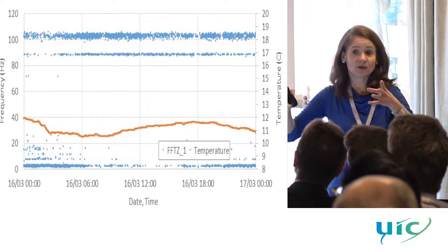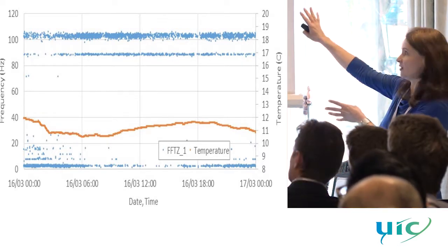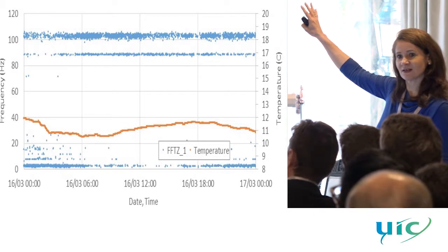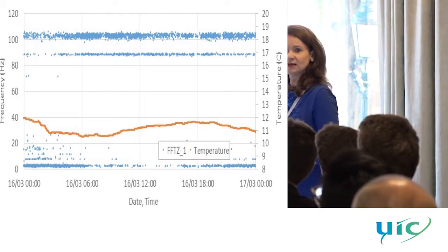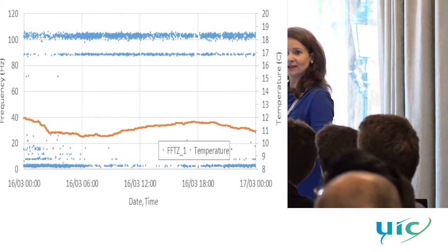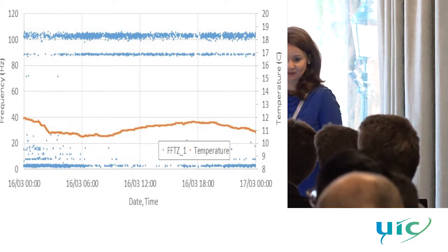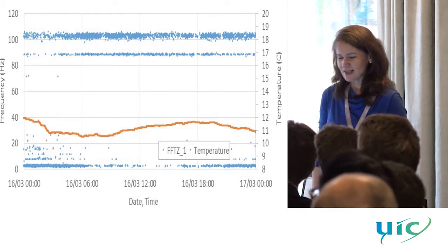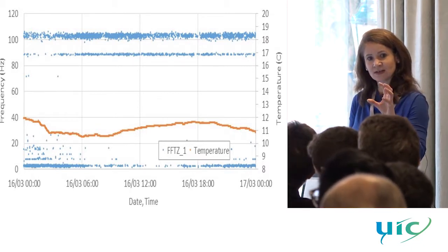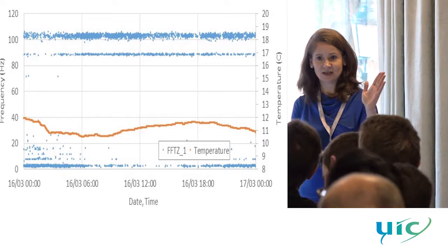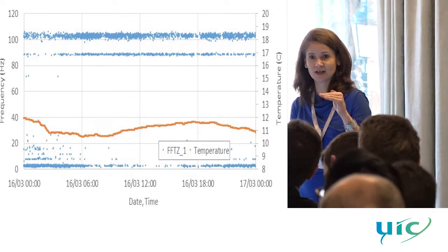Therefore, during the day, you've got more traffic loading, so the high-level frequencies relate to traffic noise, and the low level is the natural frequency of the bridge without any loading. So this is good news. That means by using the system, you can monitor any changes or hopefully pick up any change during day and night.